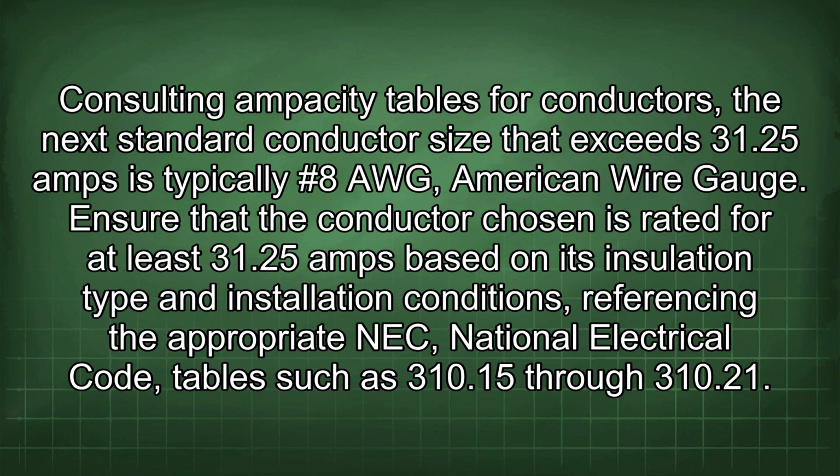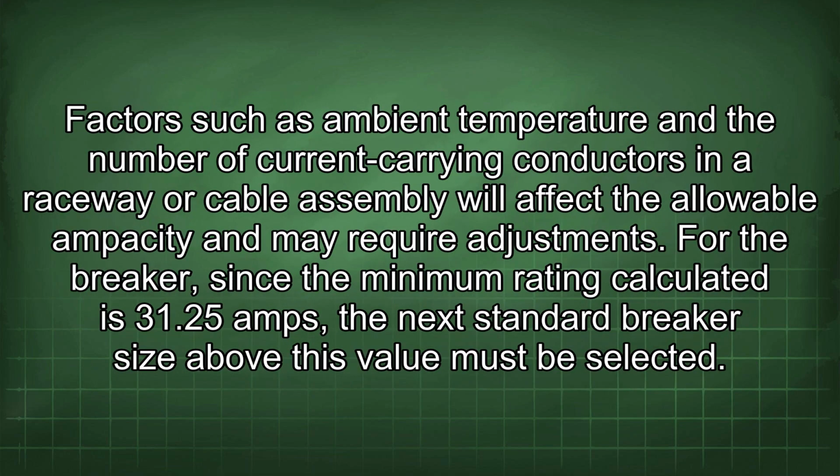conditions, referencing the appropriate NEC, National Electrical Code, tables such as 310.15 through 310.21. Factors such as ambient temperature and the number of current-carrying conductors in a raceway or cable assembly will affect the allowable ampacity and may require adjustments.